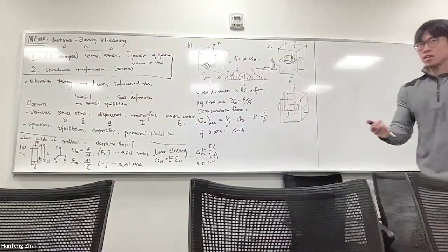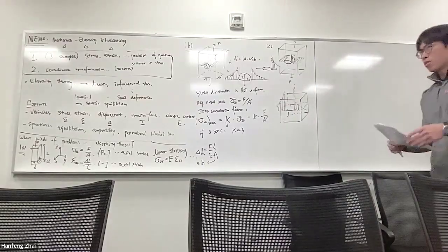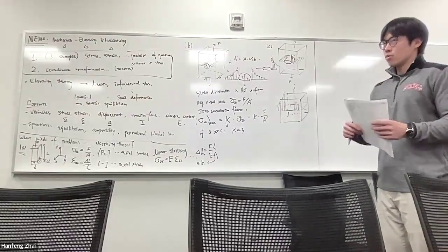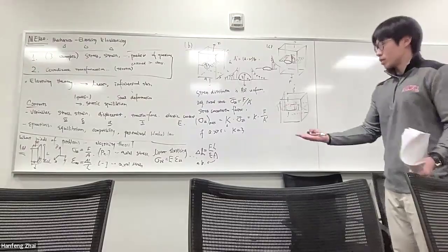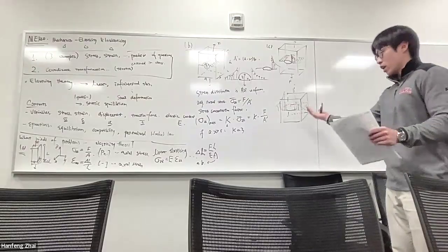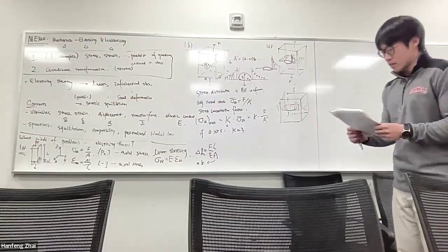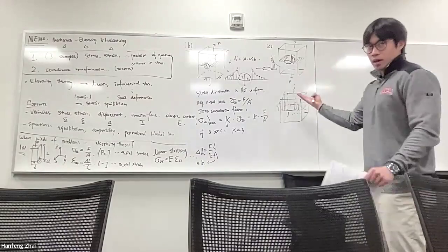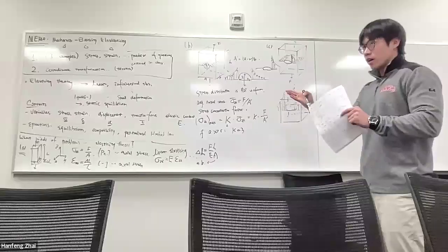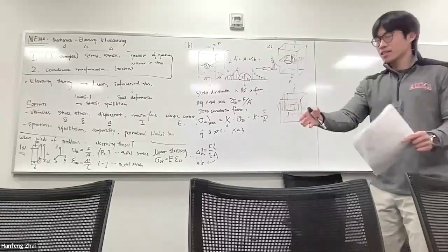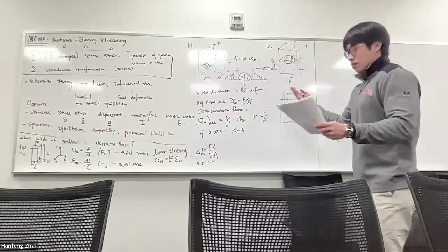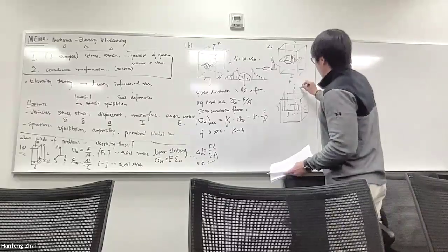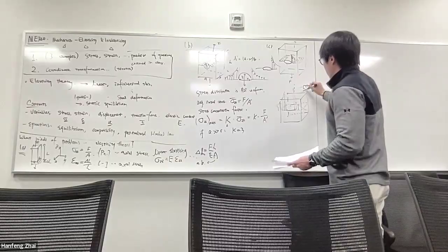And if some student asks what the physical interpretation of stress going to infinity is, we do not have a representation of stress going to infinity because stress should not go to infinity. And then you will need fracture mechanics to describe how a crack will propagate, and that will be taught much later in class. And that will help you understand why stress goes to infinity. So this is the case of a crack.